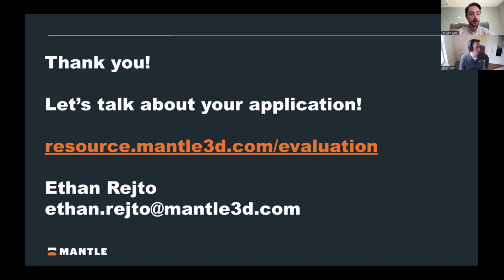What do you do? Yeah, our parts once sintered are indistinguishable from tool steels. So you can polish, stone, laser etch as you would any conventional tool steels. Right. So we've had some customers pursue surface finishes as fine as A2, A1, using single point diamond turning. But yeah, it's possible to finish our tools the very same way you would conventional tool steel.